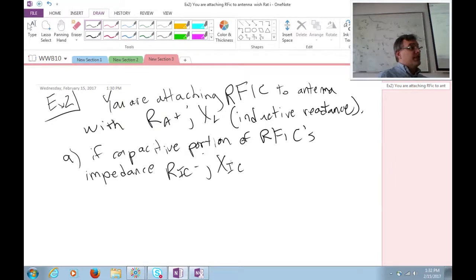The only exception there is that often the leads, when you have a chip and you're making an integrated circuit, the leads attaching to those chips are very thin wires, and that can often introduce inductance. In a few cases, enough inductance to actually resonate out that capacitance. In some instances, too much inductance, and you actually choke off the RF signal, because inductors look like close to open circuits if you get the frequency too high. So it really depends on how they've attached or packaged the chip.